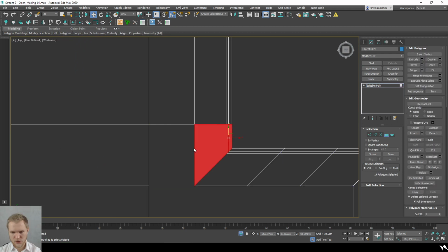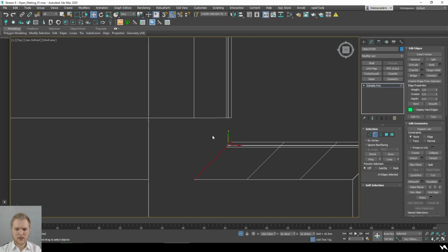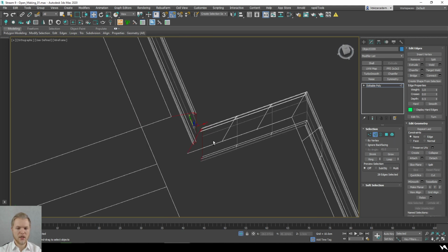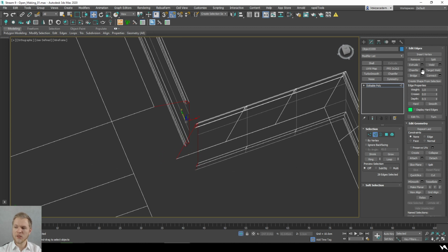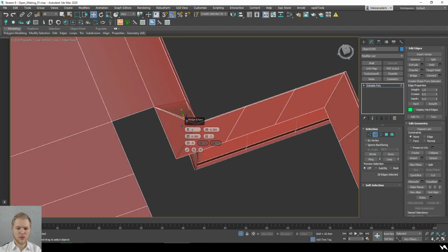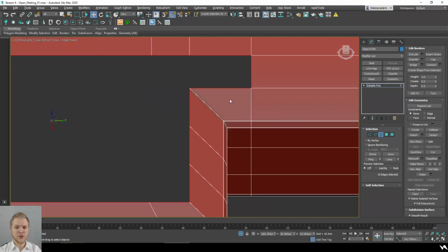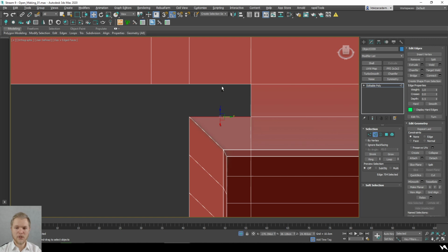You know what? I'm going to just ignore this and select this as I go. Select this, deselect, and bridge it, because this time I don't have to weld it. I'm just going to use bridge instead. So this time we just need to set it up, and let's just cap it. Rapid quad cap, which was already introduced during our course, is not really going to work here.